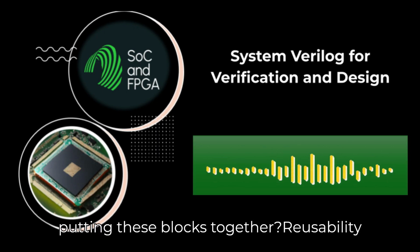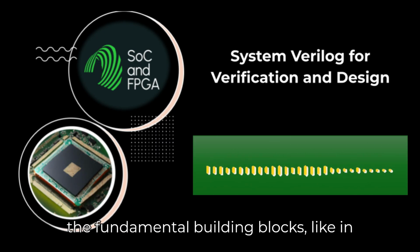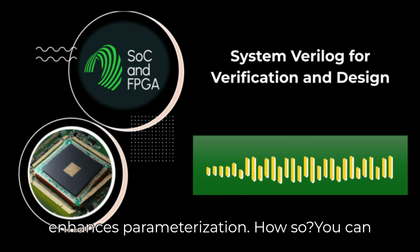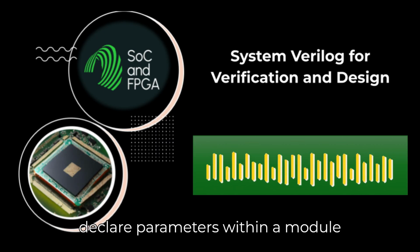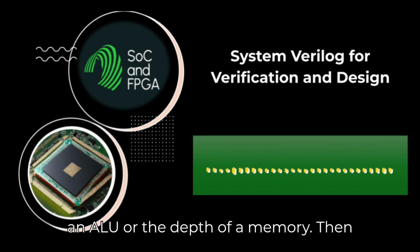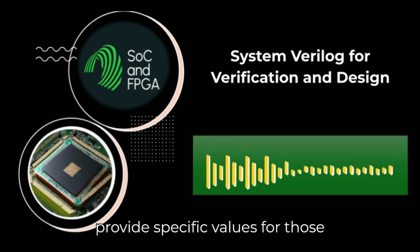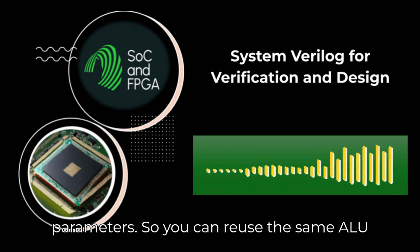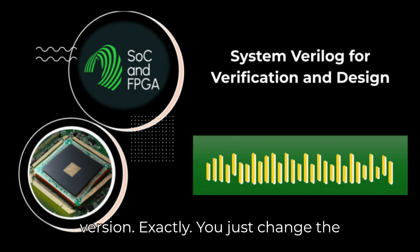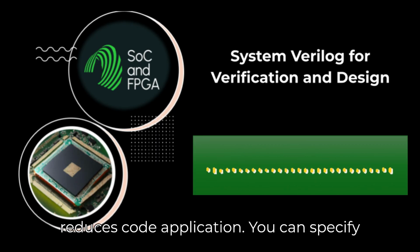What about putting these blocks together? Reusability sounds key. Definitely. Modules are still the fundamental building blocks, like in Verilog. But SystemVerilog significantly enhances parameterization. How so? You can declare parameters within a module definition, maybe for the data width of an ALU or the depth of a memory. Then, when you instantiate that module, you can provide specific values for those parameters. So you can reuse the same ALU code for a 32-bit version and a 64-bit version. Exactly. You just change the parameter value during instantiation. It massively improves reusability and reduces code duplication.